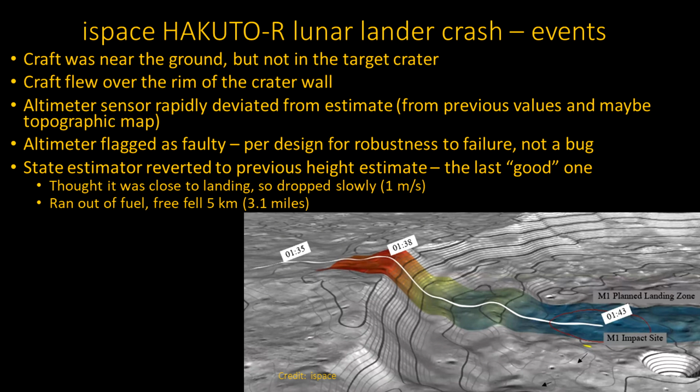We show in the more detailed Hakuto-R video how inertial navigation will drift too much unless there are altitude updates using the altimeter or other substitute data. So, this craft was doomed to a failed landing once the lone altimeter failed with no backup. The altimeter is a sensor. It didn't fail in the Hakuto-R case, but the problem was that the incorrect fault detection logic declared that the altimeter did fail. With no backup instrumentation, that guaranteed failure to land successfully.